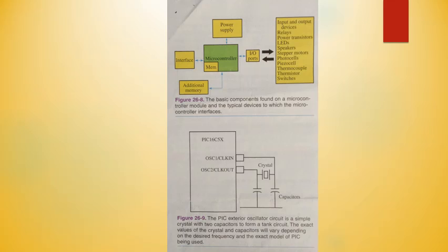The microcontroller's I/O pins can be programmed as output or input pins. When programmed as an output pin, each pin can output digital signals. When programmed as an input pin, each pin can receive digital signals. Devices commonly controlled through the I/O ports are relays, power transistors, servos, stepper motors, LEDs, and solenoids.